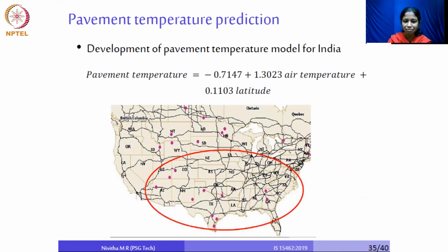So the air temperature and pavement temperature data was collected, and then a regression model was used. Again, there are many parameters which would influence this correlation. If you look at the current MEPDG, which is implementing the EICM model, the Enhanced Integrated Climatic Model, they have a set of 6 parameters: air temperature, humidity, wind speed, sunshine, rainfall, and some other parameter. They have a total of 6 parameters, which they think influence this air temperature to pavement temperature correlation.